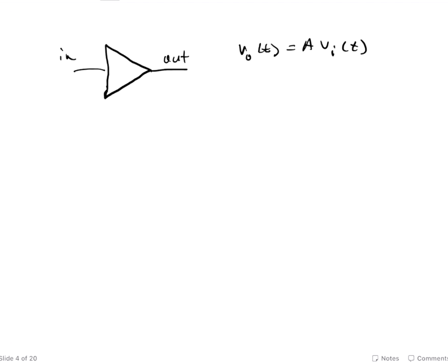But keep in mind that voltage means absolutely nothing without a reference. Voltages always need a reference. A voltage is a potential difference. It's basically an energy difference. And to understand a difference, we have to have a reference. And we usually use ground or earth for voltages. It doesn't have to be ground, it doesn't have to be earth, and there can be different values for ground.